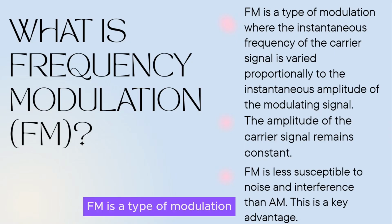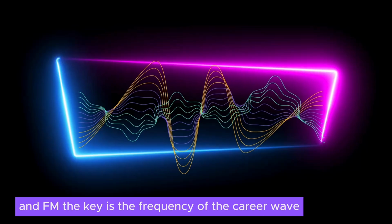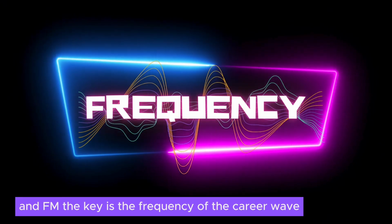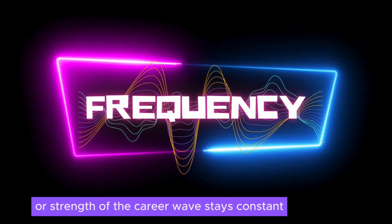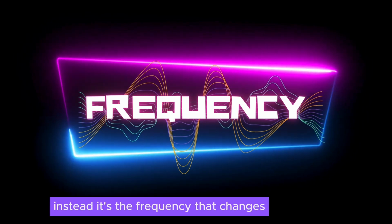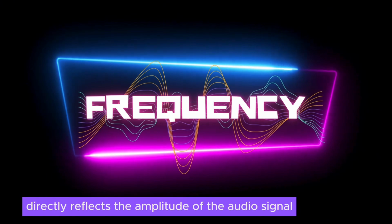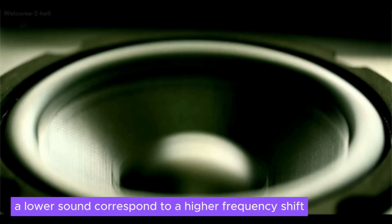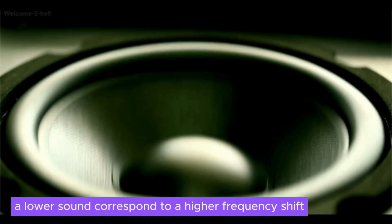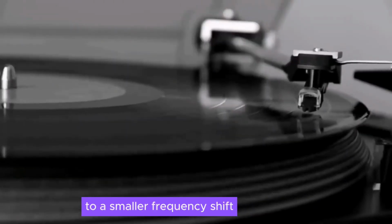FM is a type of modulation, which essentially means it's a way of encoding information onto a radio wave. In FM, the key is the frequency of the carrier wave. Notice that the amplitude or strength of the carrier wave stays constant. Instead, it's the frequency that changes. This change in frequency directly reflects the amplitude of the audio signal we're transmitting. A louder sound corresponds to a higher frequency shift, and a softer sound corresponds to a smaller frequency shift.